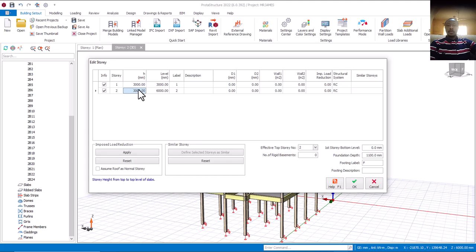Is that okay? So on that note, we are going to leave this one. Assuming it's 4 meters, I can click on this one, make it 4,000 because it's in millimeter. I can see the unit millimeter, but since it's 3 meters, this is 3,000. I'll just leave it at 3,000. That is fine. Then I'll come to this place now.